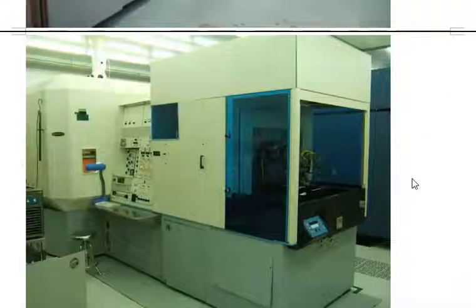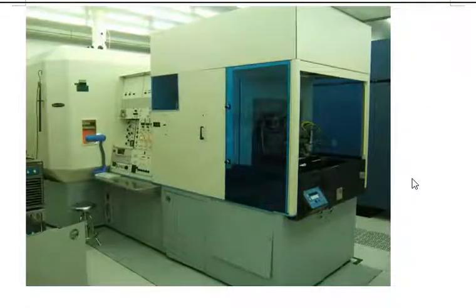This one I guess I'm more familiar with because this is very nostalgic. It takes me back to my ion implant days. This is one of the ion implanters that we had in our laboratory, and this is a variant, and the source is way back here next to the wall, and this is where you put your wafers. This has a rather nice feature. You can do what they call heated implants. So we would heat our wafers up to 600 or 700 degrees sometimes as we do the implant. This is all the controls, and I can tell you it was not simple to control this.